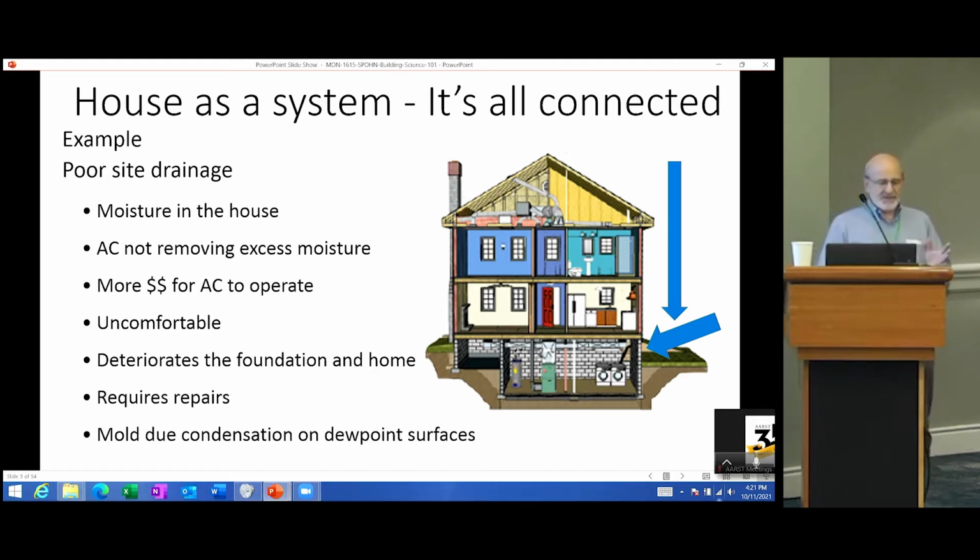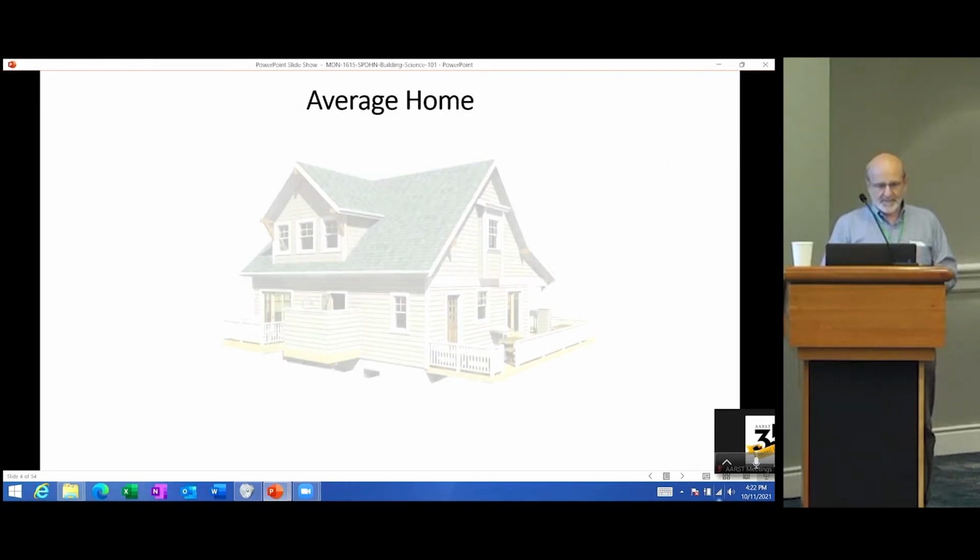And a lot of this is due to the vapor, the excess humidity in the air coming into contact with a condensation surface, a surface that's below the dew point, and you don't always know where that surface is. It can be on your surface, or it could be a surface buried inside the materials of construction, or in a place like a crawl space where you never visit and you have no detection means down there. So getting this all under control is very important.